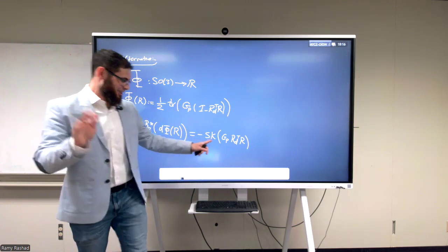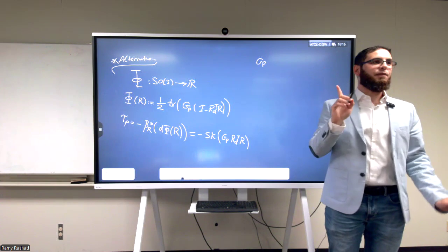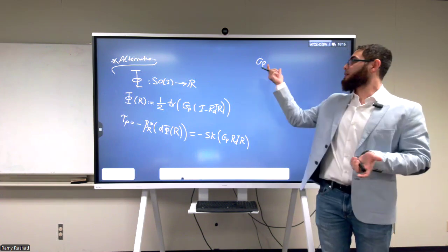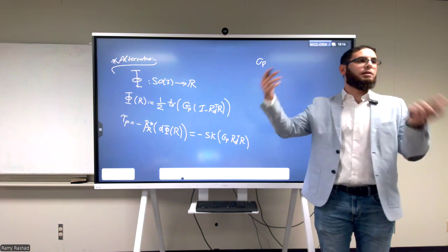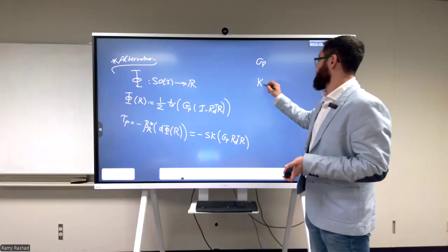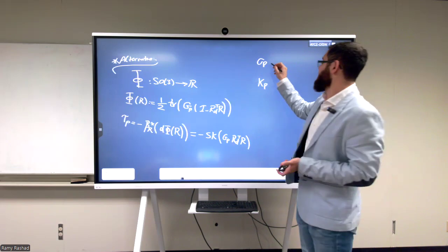Interesting. Okay. So this GP is called the co-stiffness matrix. It's not the stiffness one. Very similar to the idea of a vector and a covector, but this is now a co-stiffness matrix. Just like I have a stiffness matrix, you're used to the stiffness matrix between this one, and this is known as the co-stiffness matrix. It's given by this expression.